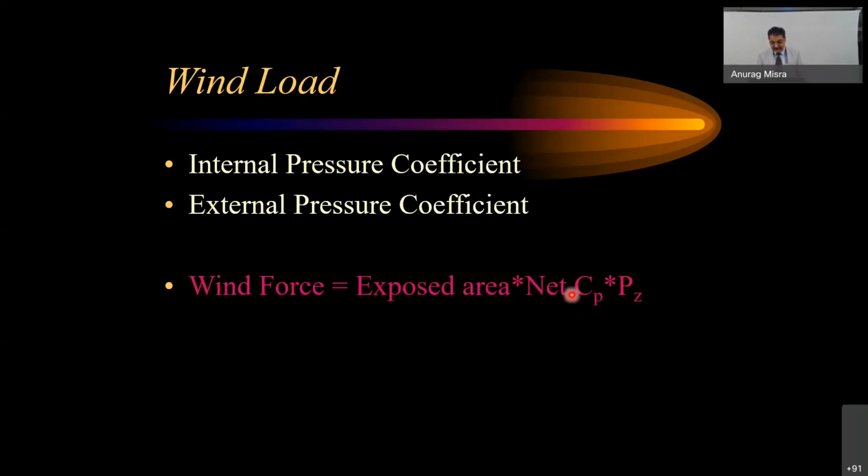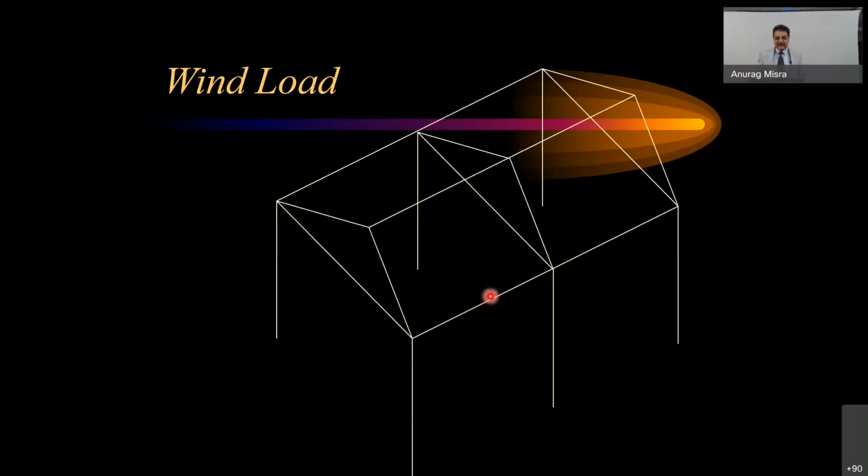Wind force we calculate from this net Cp and Pz, that is your coefficient and design wind pressure, and these are applied on the structure for the analysis purpose.